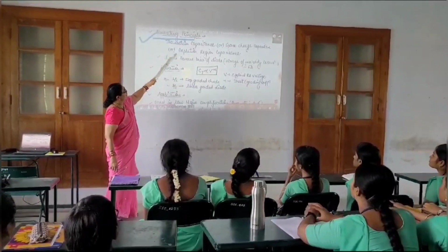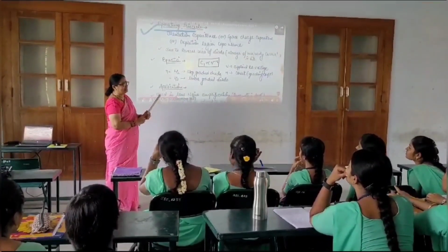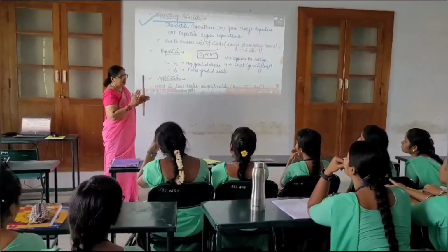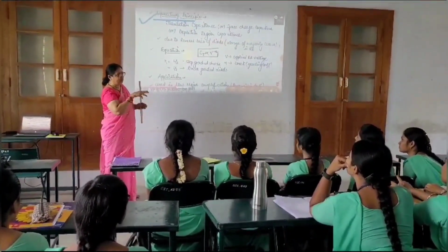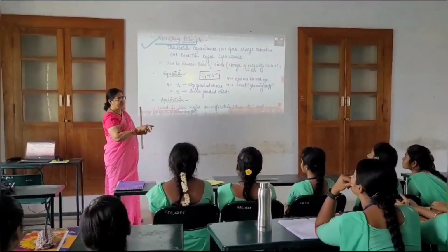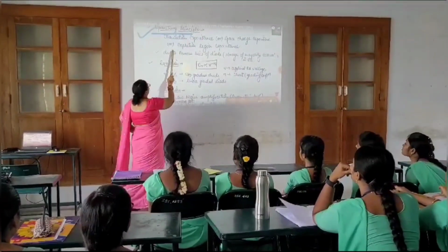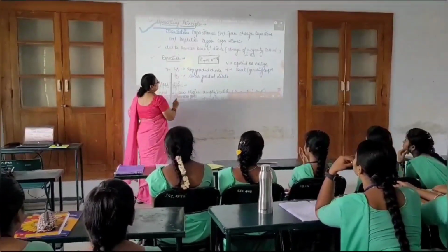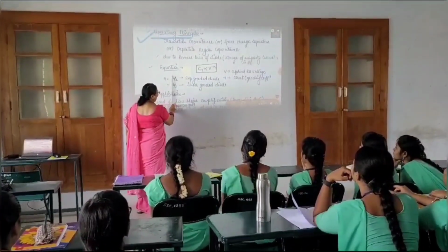This makes the net phase difference of the signal fed back to the Wien bridge network 360 degrees, satisfying the phase shift criterion to obtain sinusoidal oscillations. However, this condition will be satisfied only at the resonant frequency, due to which the Wien bridge oscillator will be highly selective in terms of frequency, leading to frequency stabilization.